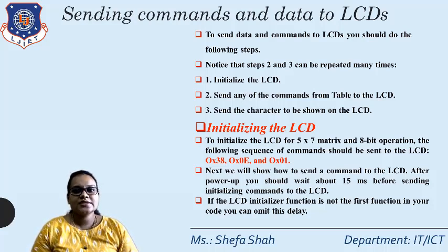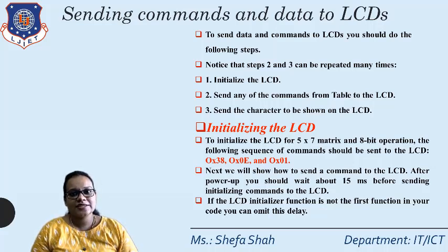So to initialize the LCD for 5 cross 7 matrix and 8-bit operations, the following commands should be followed. First, 0x38 for receiving the 8-bit data, then 0x0E, that is display on cursor blinking, and 0x01, that is clear display screen. So these 3 commands we will write and give to the LCD screen for this particular initialization.